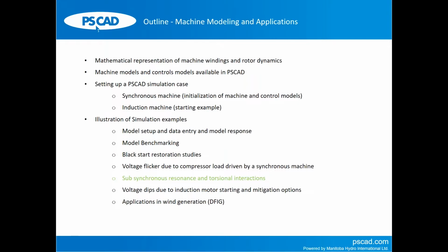I will take a simple example and show how the machine models can be connected and set up for a simulation in PSCAD. I will show you a very simple single machine infinite bus type example, which I have been using for the past 20 years whenever I want to add a machine model to my simulation network or circuit. I will show you how I use my simple example case and just copy paste the structure of the model into the circuit that I want to study.